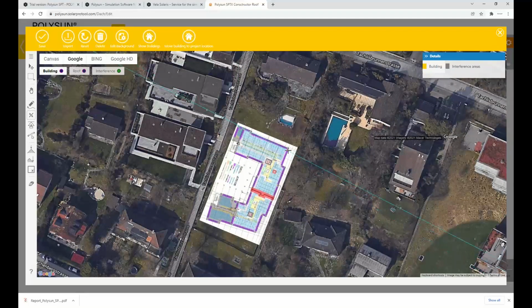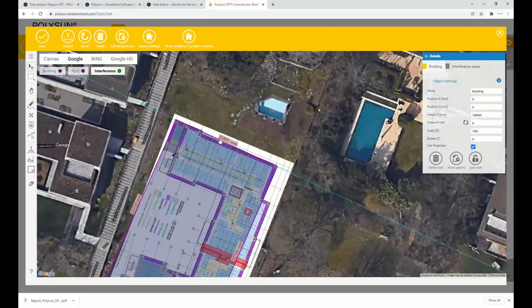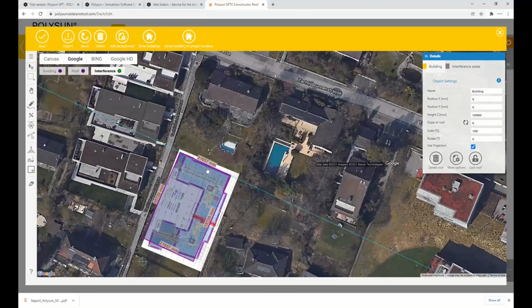Once you're done with editing the background, you can click on Save Background, and as before, you can start drawing guiding lines and you can start drawing your building. I will just simply demonstrate how it works. You could draw completely the whole structure. I will just really simplify it, draw it like that. And you can see now it also shows the length of the building. And now actually you can compare, no, it should not be 21 meters. I actually know it should be 23 meters.